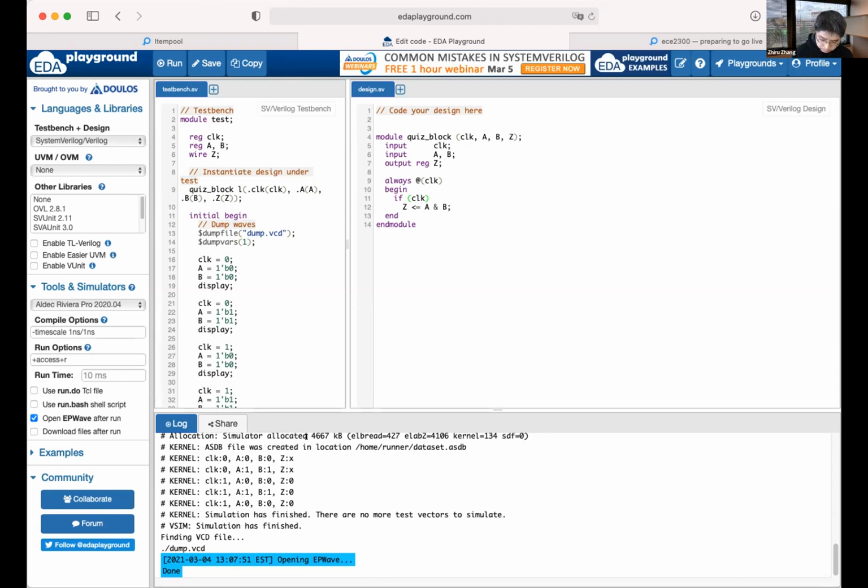Okay, so how do you fix this? How do you make it a latch? Any suggestions? I can see the chat window now. So Lauren is saying posedge. If you put posedge there, we can do the edge thing. You're talking about this one, put it here. That means we make Z sort of like a flip-flop. It's becoming edge sensitive.